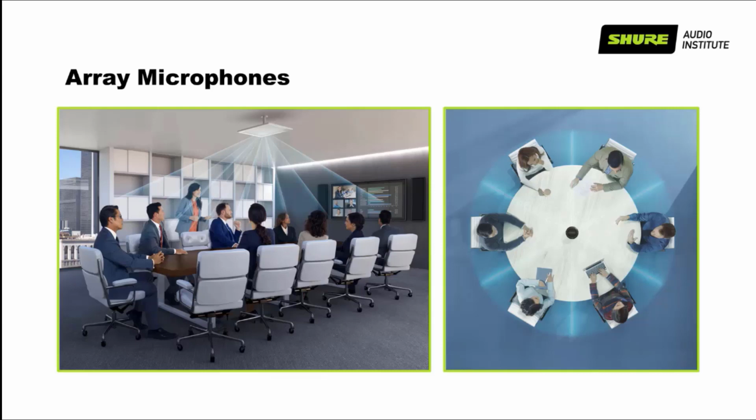And in the picture there, that one is the ceiling array mic, which can put out 8 different lobes at the same time. And the reason that it's very useful is because you can electronically aim those lobes wherever you want. So if you've got seats around a table, you can point a lobe at each of the seats or every 2 seats or whatever works out, and you can electronically change the width of the lobes. So you can define whether you want a really tight pattern on one seat or a wider pattern that picks up 2 or 3 people, whatever makes sense for that room. The nice thing is it doesn't require any physical repositioning of the microphone or physical adjustments. It's just all done electronically.